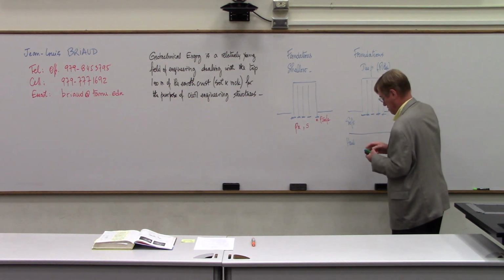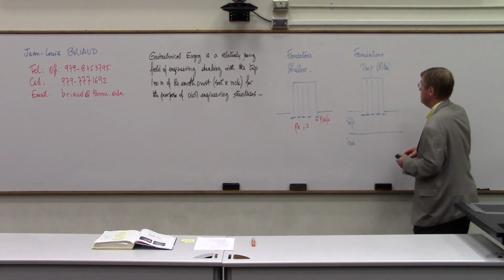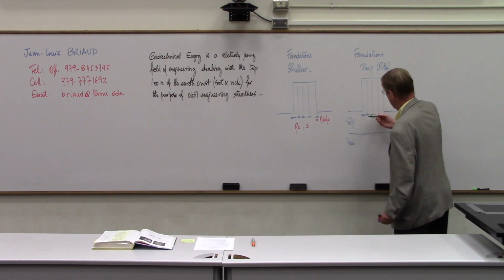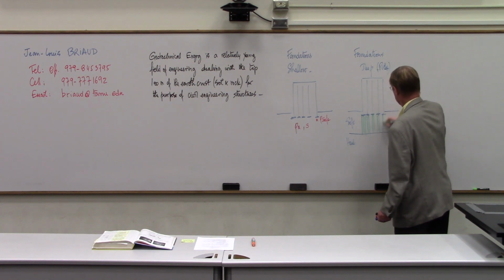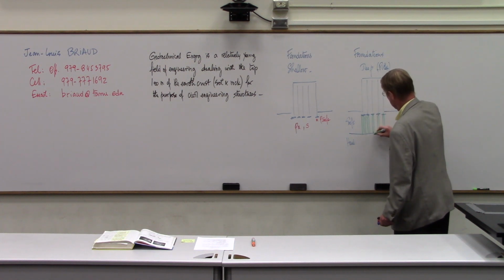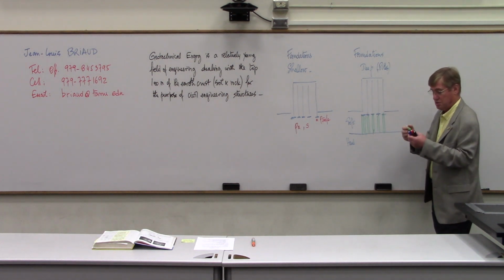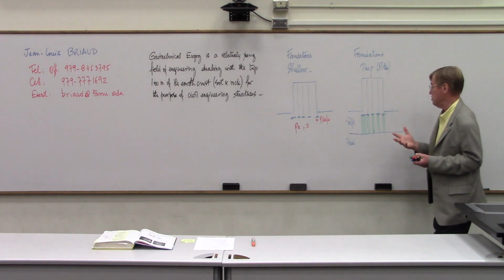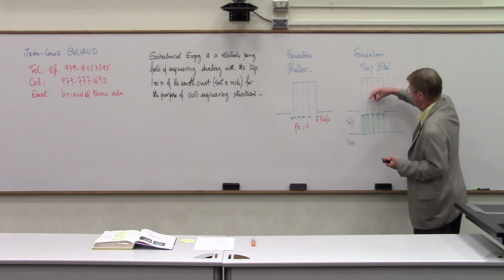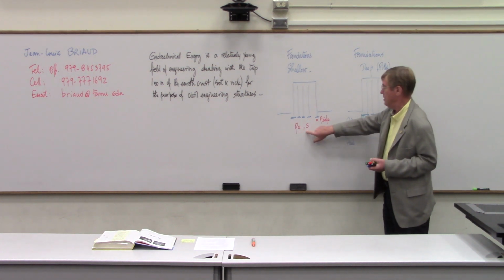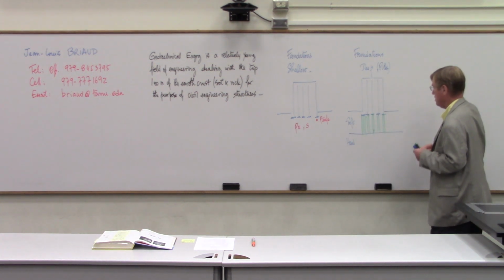And then here, we say, well, we need to drive some piles, and we'll put some piles under those pile caps and transfer the load of the building to the hard layer through those, essentially those columns, if you wish, in the soil that we drive, so that the weight of the building is transferred to the hard layer, and then we can satisfy the same two things.